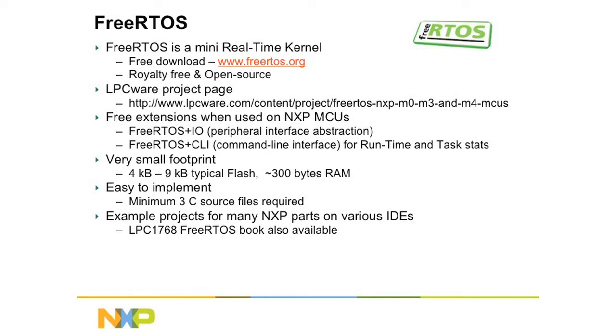FreeRTOS, like I mentioned, the RTOS of the LPC Open Platform package, royalty-free, open source. One thing about FreeRTOS is also that you can get commercial support for it. So FreeRTOS is like the open source version. There's OpenRTOS and there's SafeRTOS that is based on the same kernel.